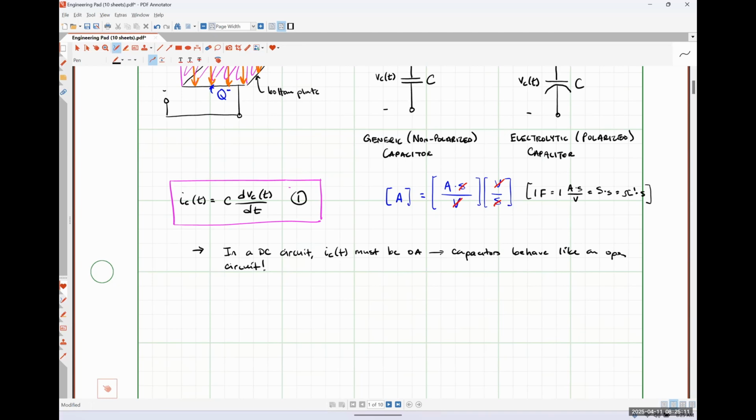In doing so, it would generate infinitely large voltage spikes, right? We talked about that. Well, in a capacitor, we'll find that the voltage drop across the capacitor cannot change abruptly, because if it does, it generates infinitely large amounts of current. Okay. So I'm not going to bother with the derivation for that, because we've already seen that exact behavior when we were talking about inductors on Wednesday.